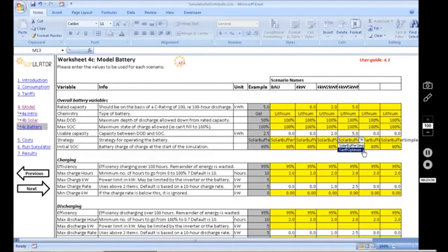It's not all plain sailing, because obviously that forecast is not always going to be right, especially with the simple rules that are built in at the moment, as I mentioned. And if you pre-charge the battery more than optimum, then you're not going to have enough room in the battery to store all of your excess solar generation during the middle of the day. So you'll end up exporting more of that solar generation out to the grid for little value.